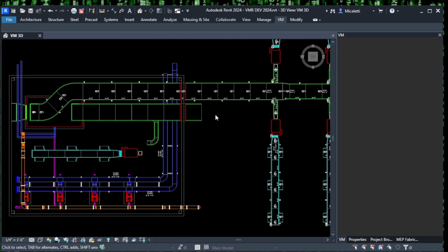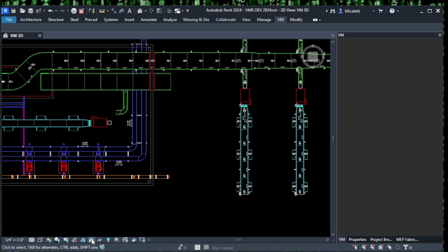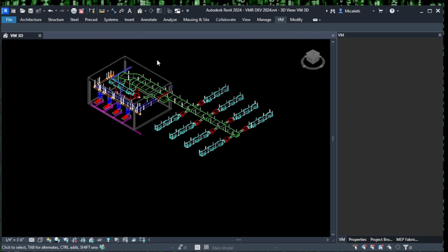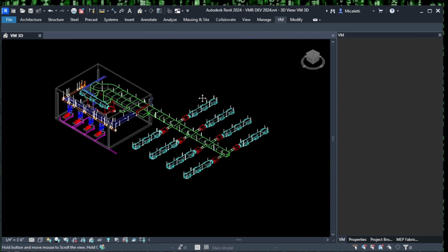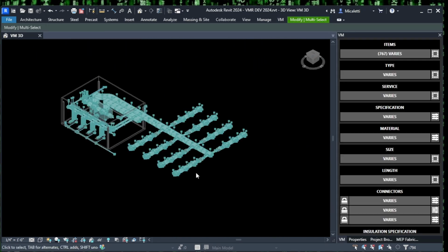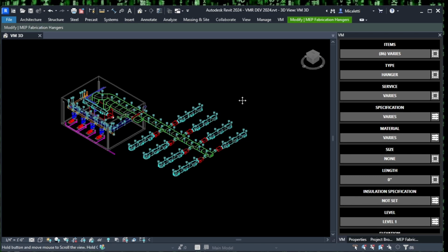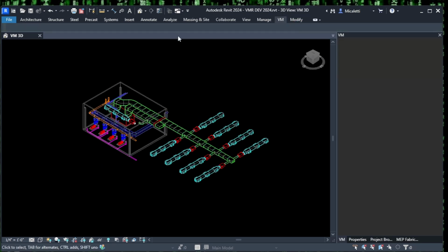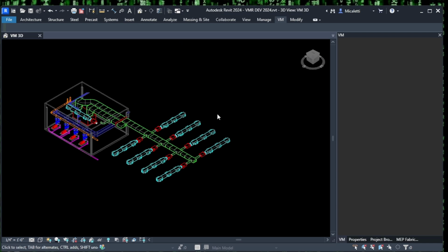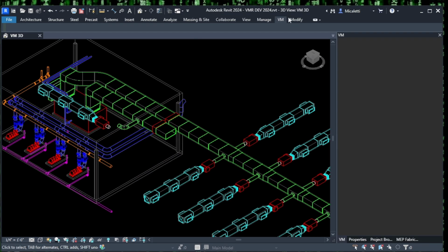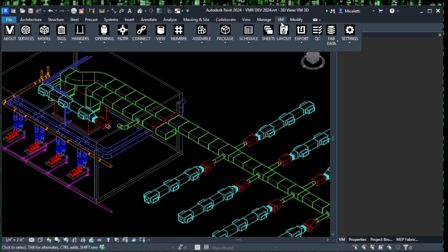There is that. We covered hangers, tags, openings. Let's unlock the side view here. Another thing we could do, which is really nice for this tool, I'm going to select everything and I'm going to say, just give me hangers. Bam, that was easy. Delete them. So now I have a clean model to work with, and I'll show off some of the openings.